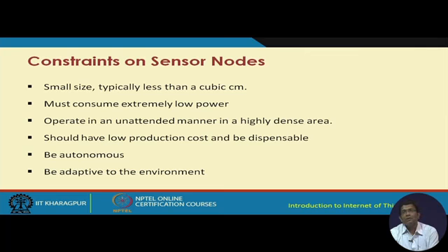One very popular operating system used for sensor nodes is known as the Tiny operating system, TinyOS. Okay. So, these are the different features, and now let us look at the different constraints on the sensor node. These sensor nodes are typically small in size, low powered, and resource constrained in all different ways. Although they are acting as small computational devices, they are heavily resource constrained in all the ways you can think of. Due to their small size, typically in the order of a few cubic centimeters, or they can be a little bigger if it is not a MEMS based sensor.